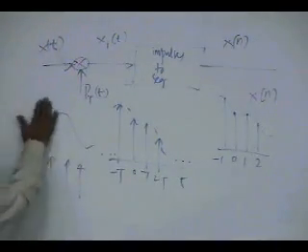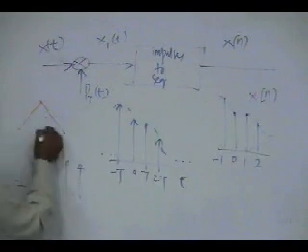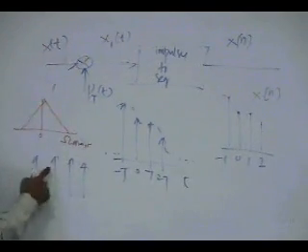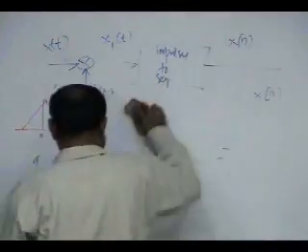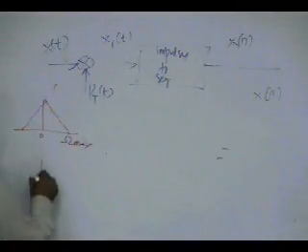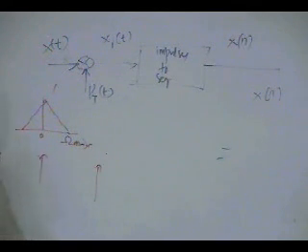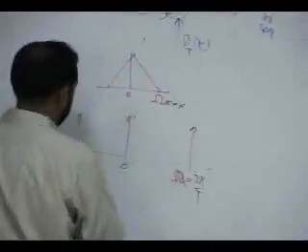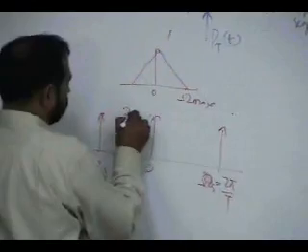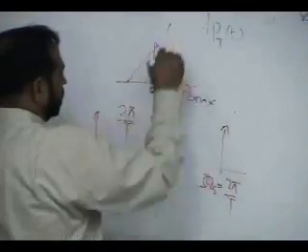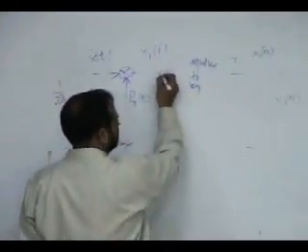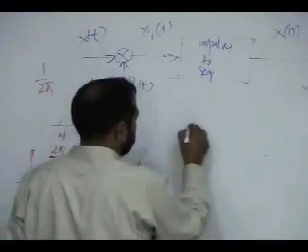In frequency domain, this signal is band limited. You say, okay, this is a band limited signal, 0 to omega max. The train of impulses is a train of impulses, but now at every omega s. You can call this omega s, which is 2 pi over capital T, and the magnitude is 2 pi over capital T. So multiplication is convolution, with 1 over 2 pi. So what you get here in frequency domain is copies.